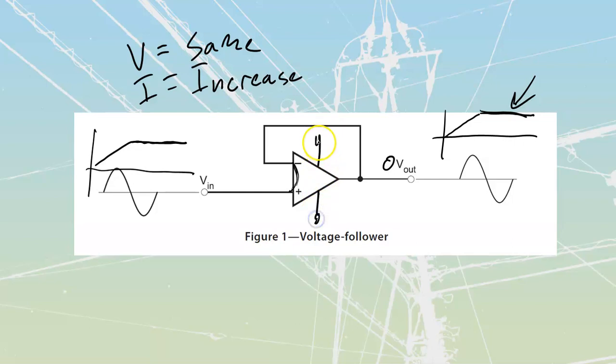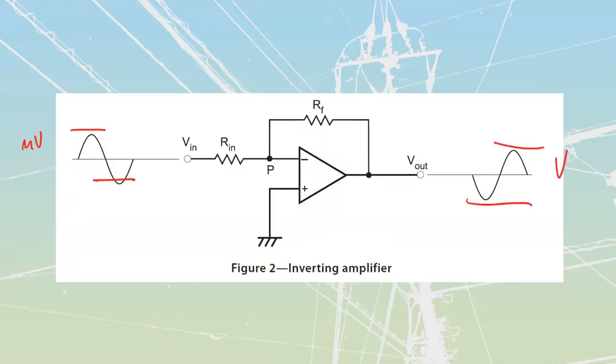And it does that by passing it in from those outside arms. This one over here, we now have two resistors inside of it, RF and RN, which are going to form a voltage divider. And that voltage divider is then going to give us the amplification that we would need on our applied side. Because what we'll have is a voltage drop, RF, over here, over top of my RN that we are going to feed out over here. How does this thing work?